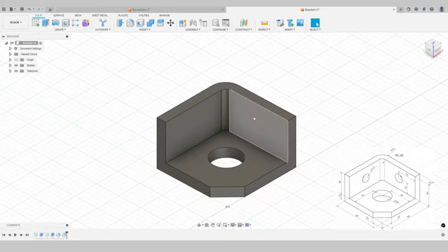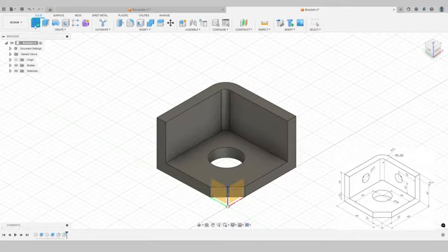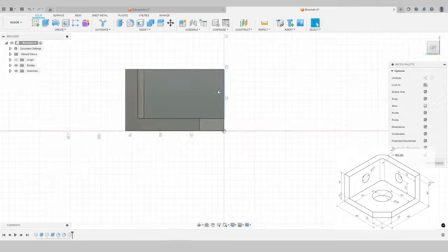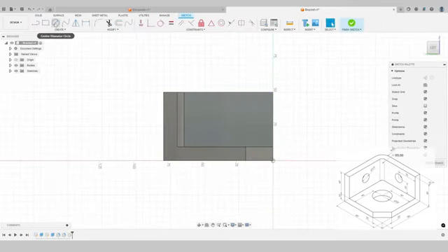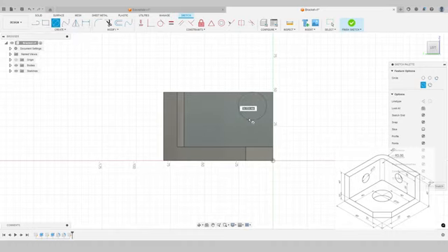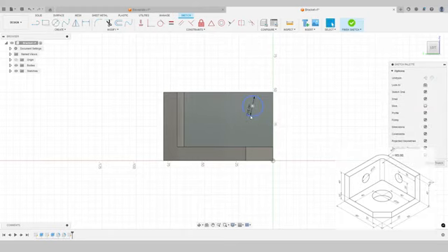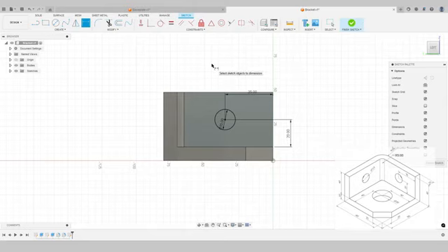We've just got two features to add here. One is the hole on this wall and the other on this wall here. So to do this, we want to sketch on this wall. Let's create a sketch. We'll select this face here. Looking perpendicularly, let's select the center diameter circle. Again, I just draw that in anywhere for the time being. That's got a diameter of 15 mil. Press enter. And a sketch dimension circle to the vertical. That is 35. And then circle to this face here is 20 mil. The circle's in black, fully constrained, looking good.